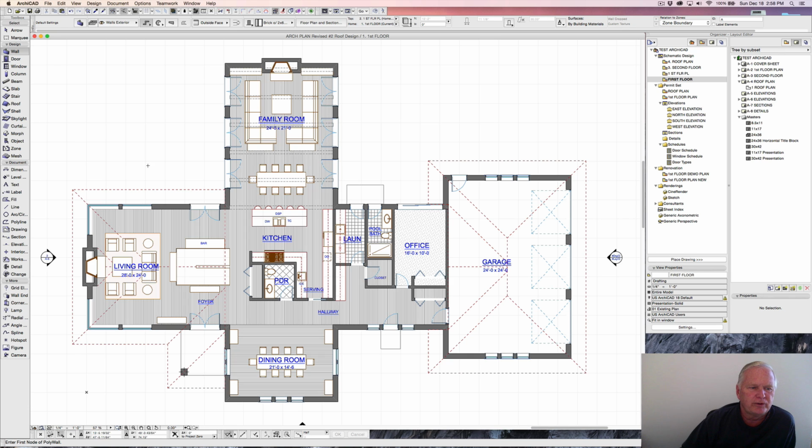And now what we want to do is take all these exterior walls that we created and change them to that wall. So in order to do that, we could go around and change every wall, or in fact the easier thing to do is the following. We're going to go up to an icon up here just under the word design, but not under that menu.